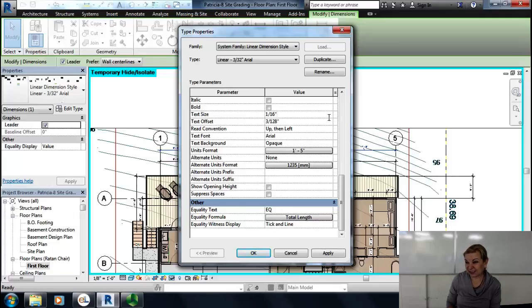But you don't have to pick the standard 16th or 1/8. You could go in between. So that's one flexibility that I don't mind if you use, because we're printing in small scale. I'm printing my project on 11 by 17 sheets in 1/8 of an inch. And if you're printing in smaller scale, Revit is going to beef up the text size so it's clear to read.